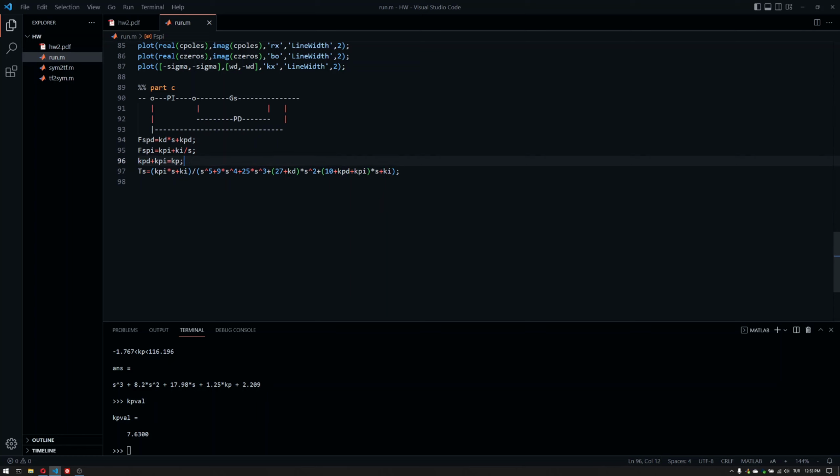What we do is we introduce this multi-loop structure here, and we divide the proportional part into KPD and KPI. And basically, based on the KI value, we can decide on KPI directly. Then we will push the zero away. Once we have that KPI value, we can come up with a KPD value that will give the sum equals KP, and you will end up with KD, KP, and KI.